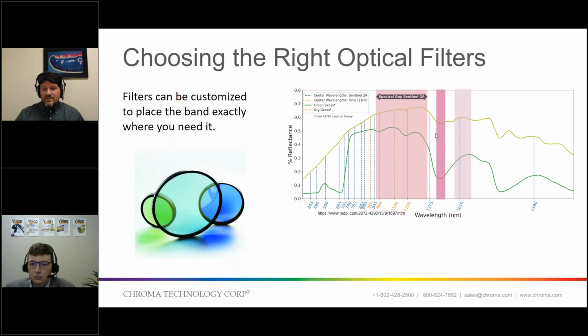In the case of remote sensing, you have a lot of ambient light and sunlight, so really there you're just trying to squeeze down the spectral bands of interest and get rid of the rest. So certainly ambient light has to be taken into account when considering filters.